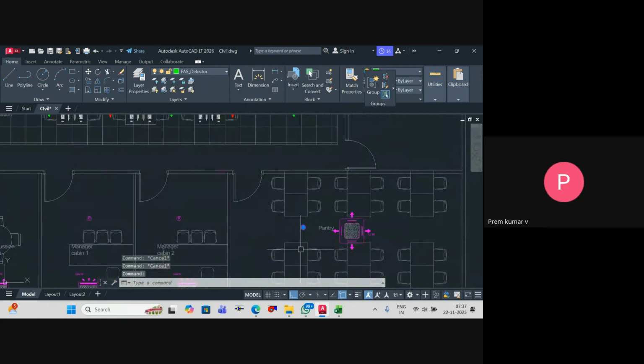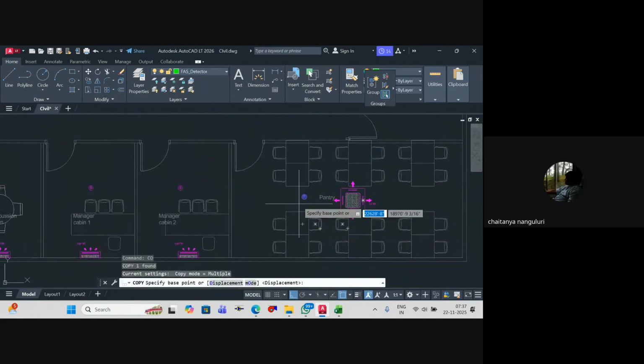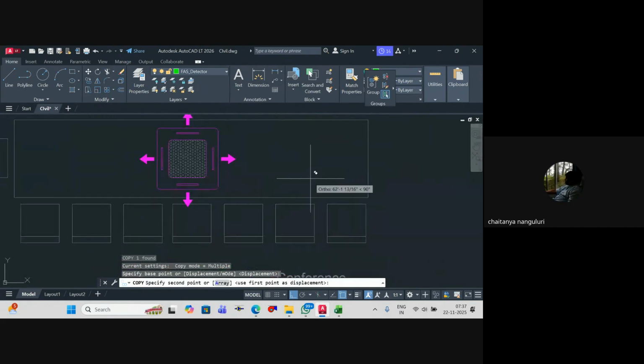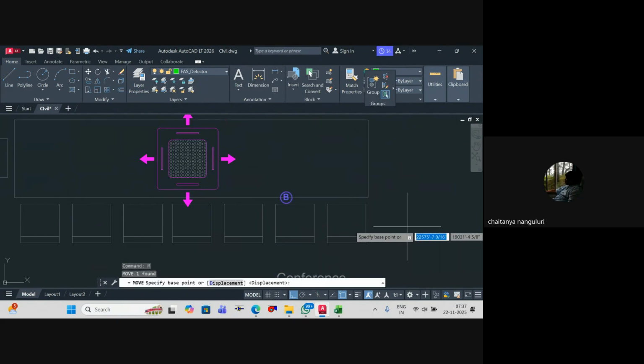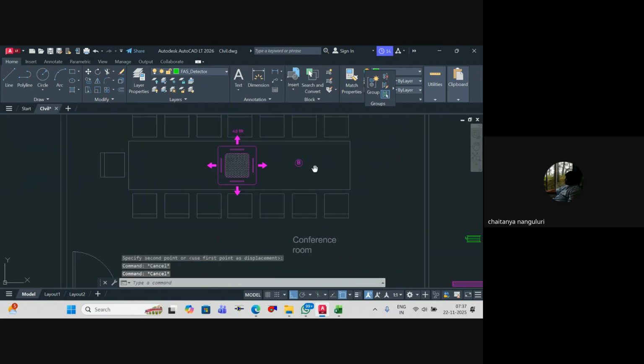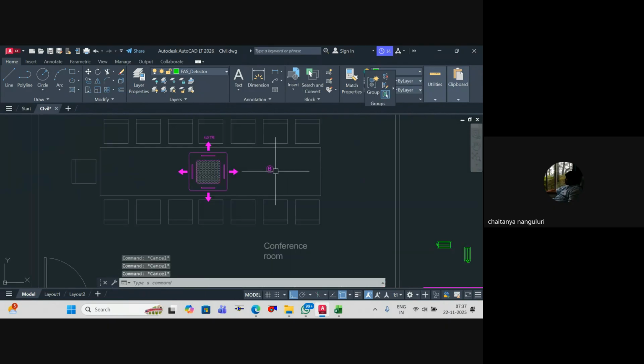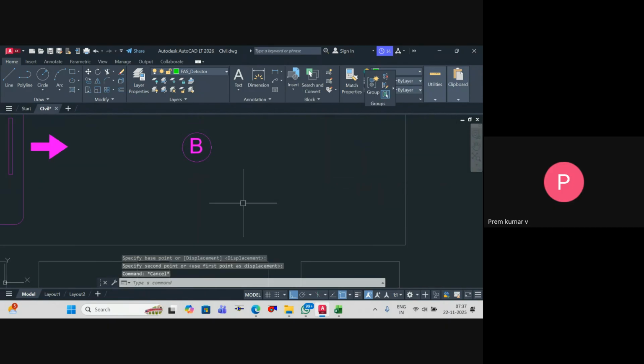So this will not be a smoke detector in the pantry. It will be a heat detector, not a cooking detector. A heat detector is preferable. In general lunchrooms you don't have any steam. If you have cooking, yes, it's important, but in a general pantry you won't cook there. You'll just bring lunch boxes and open them, so you won't have any smoke because of it. So you can ignore it.